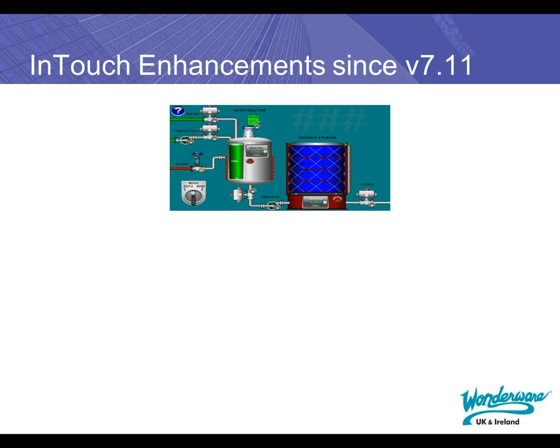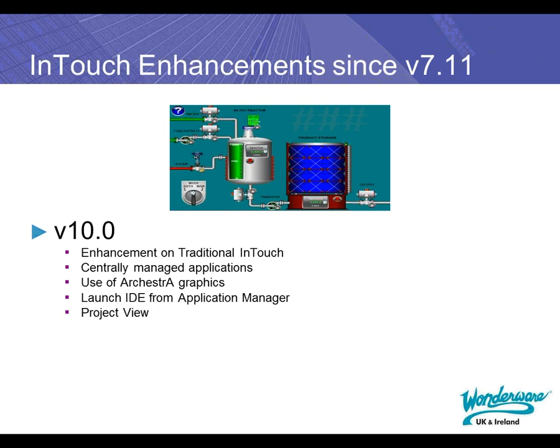InTouch HMI version 10 is an enhancement of traditional InTouch. This is where we will start seeing the changes with introducing Orchestra graphics. As stated previously, it provides a more tightly integrated connection with the Wonderware Orchestra environment, enabling the use of centrally managed applications and Orchestra graphics. It also includes a button to launch the IDE from Application Manager, and the appearance of the Application Manager window has been updated to current Microsoft standards.